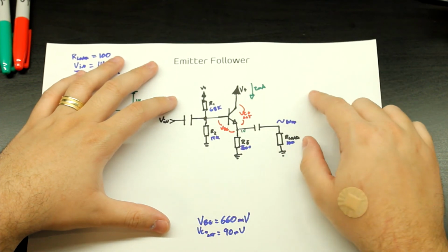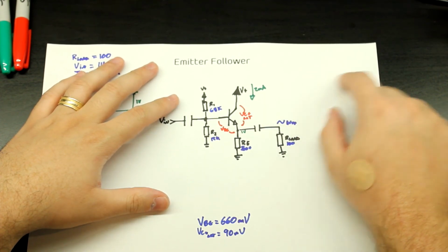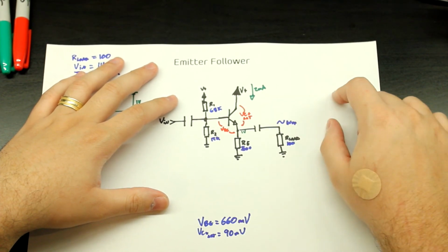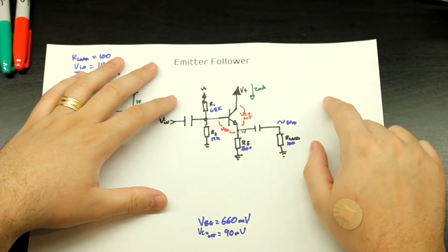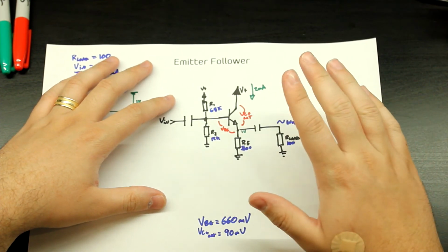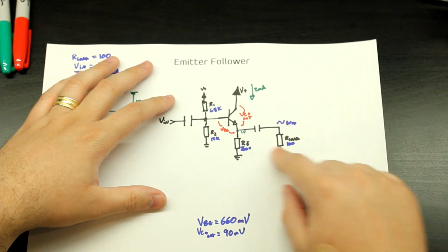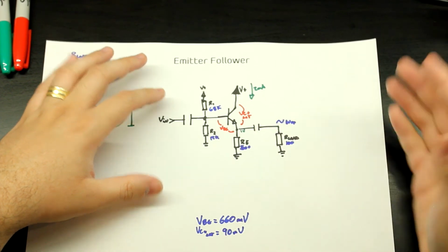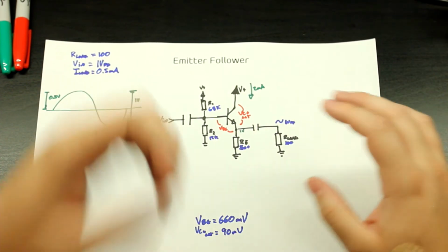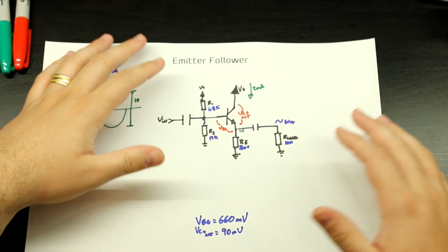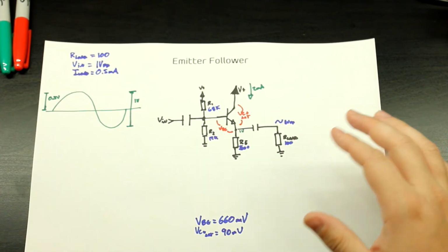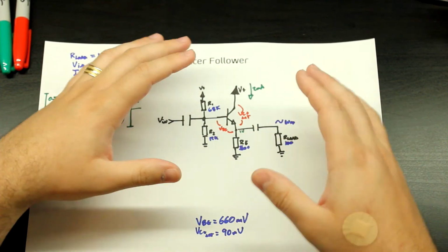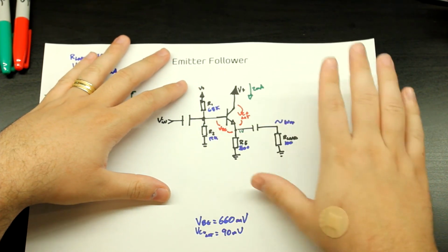Don't mess around with the, I think it's 1 over 2 pi RC. Yeah, I think it's 1 over 2 pi RC or something like that, which is just the formula for the 3 dB cutoff. You don't want to have, for example, your 20 hertz at minus 3 dB, because that's like half of your input. What you want is to have the least amount of attenuation possible. I always strive for less than 1 dB of attenuation at 20 hertz. The less attenuation you can get, the better.